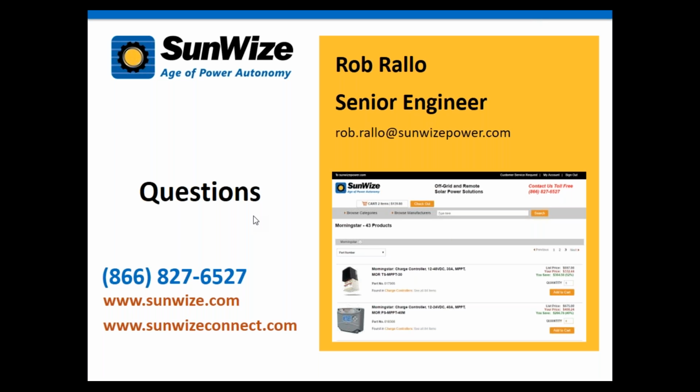Okay, thanks. I do have one more final question on explaining one more time the function of the bypass diode within the solar module. Okay, again, what the bypass diode does is when that cell or a few cells are shaded, those cells are going to want to take current. Remember, it's kind of like an LED in reverse. So when they get shaded or when the sun goes away, those cells are going to want to take current.